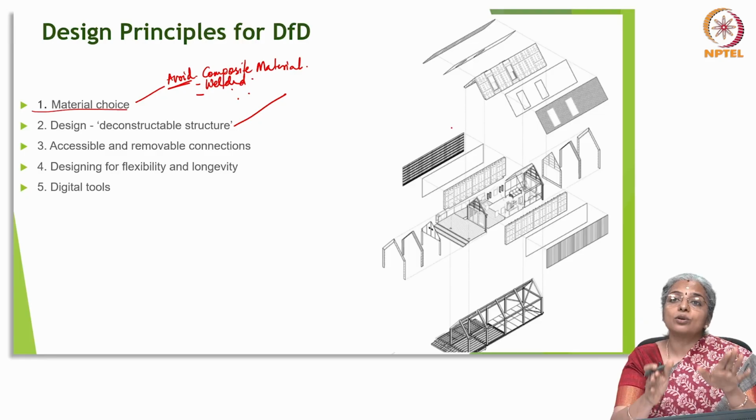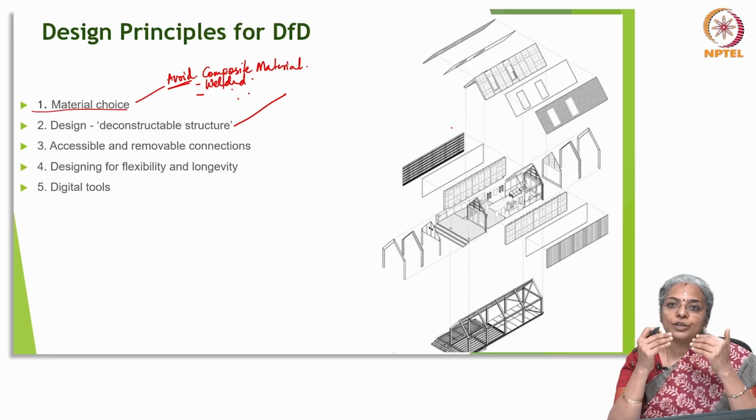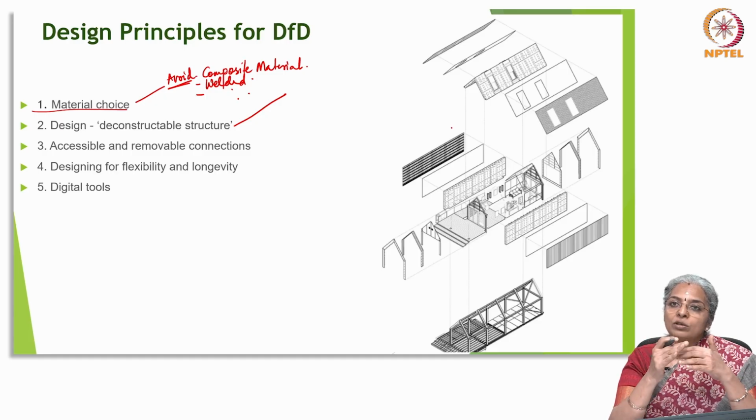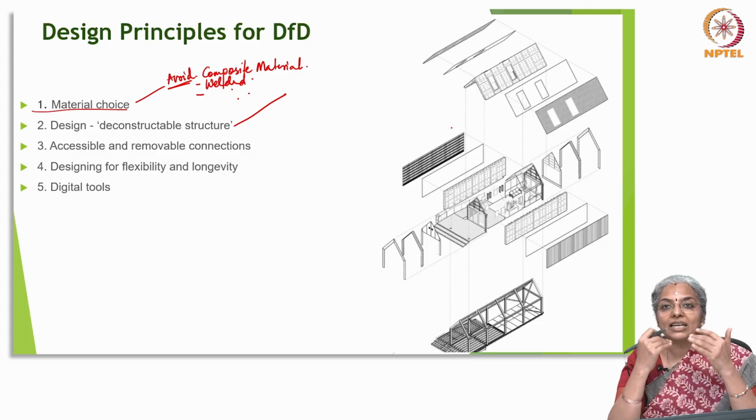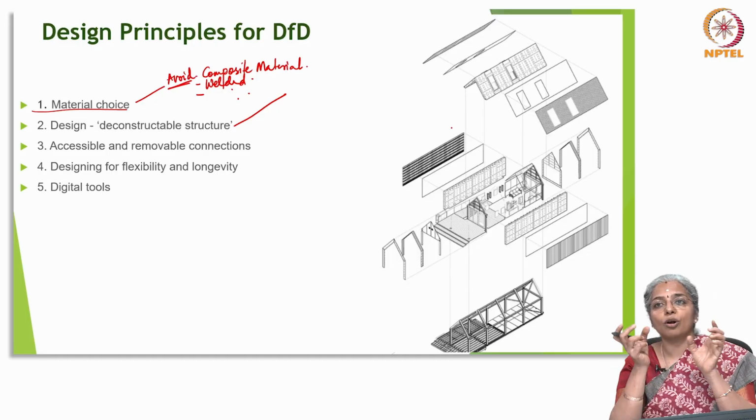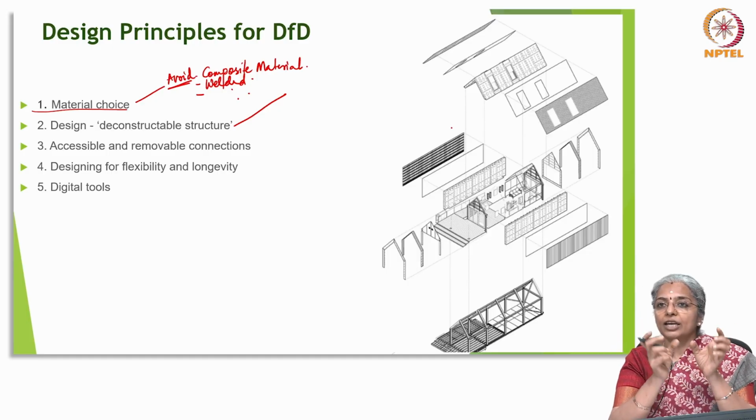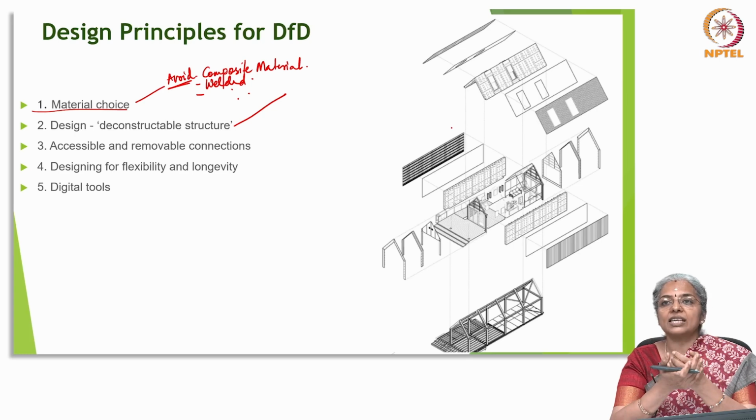It will also permit ease of deconstruction. So, we should provide adequate tolerances and also minimize the need for destructive demolition. We should start using standardized sizes or modularity in the components because this can ensure better recovery and, most important, better reuse steadily for a longer period of time.